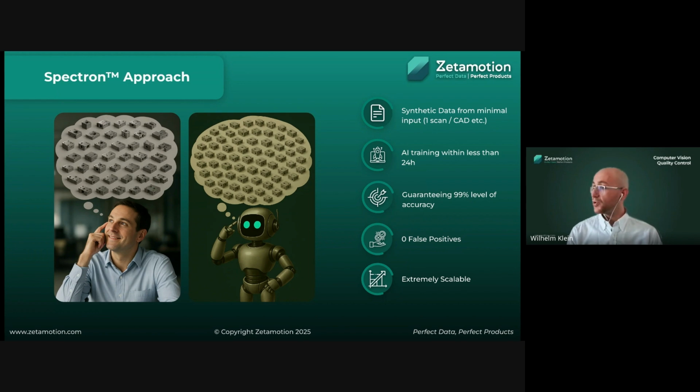Instead, you show one or two examples. Right? So you have a seasoned QC worker sit down and show a couple of examples and explain, okay, look, there's this scratch here. And the scratch sometimes happens when humidity in the factory is too high, and because of that, one of the production steps has a bit of a hiccup, and one of the wheels misaligns, and then you get these kind of scratches in there, or sometimes the bubbles happen on the coating.